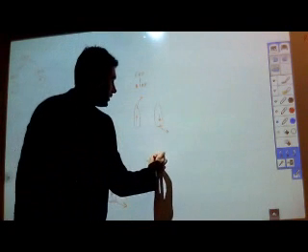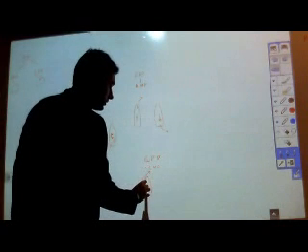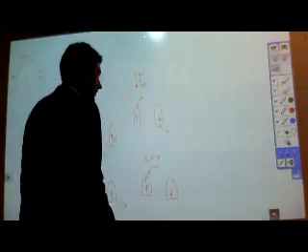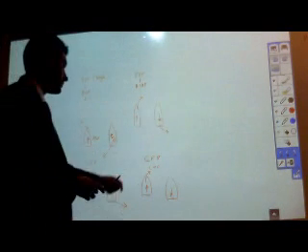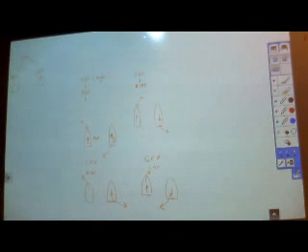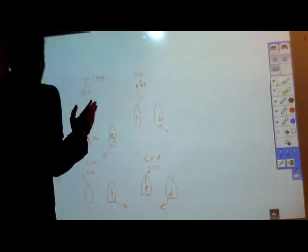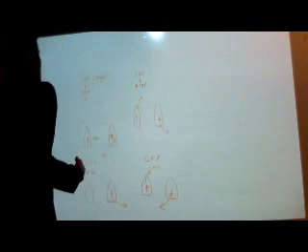Again, for a CPP left-handed propeller, when you go ahead, there is not going to be any change. But when you go astern, it will start behaving like a fixed pitch right-handed propeller going astern. So the stern is going to go to port. So again, remember: a fixed pitch right-handed propeller is going to do like this, but a CPP is going to go ahead and then come astern like this. Okay?